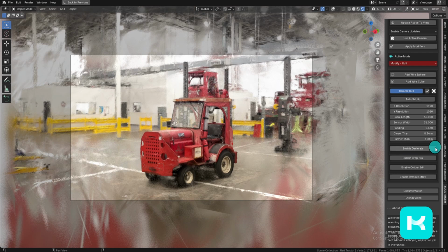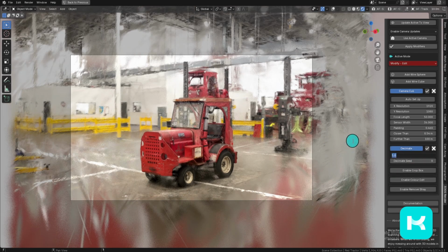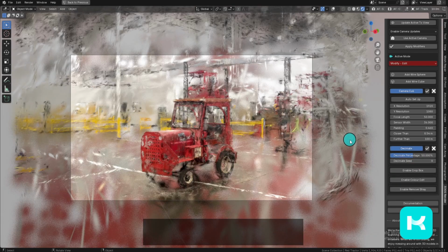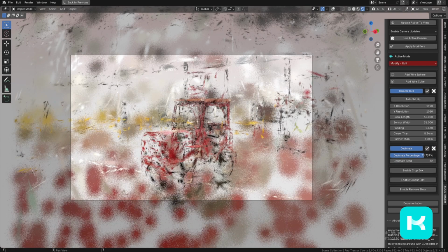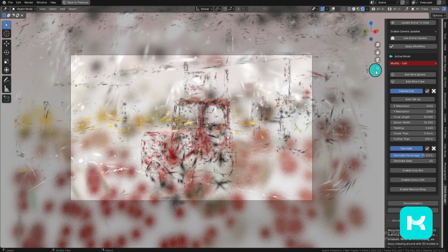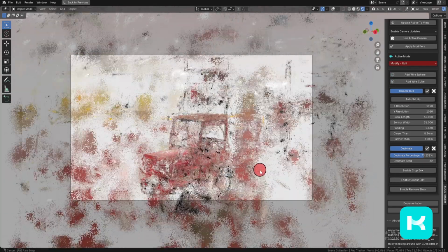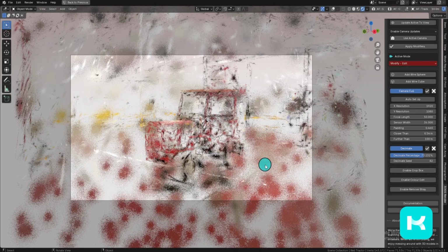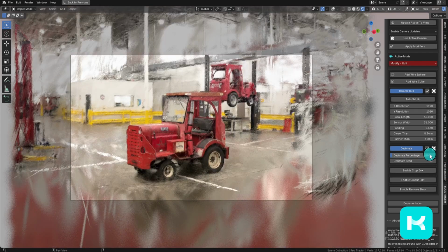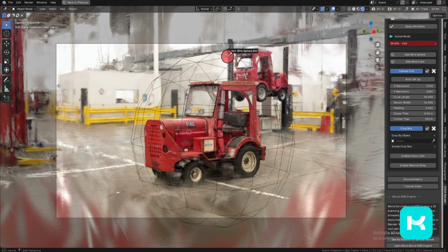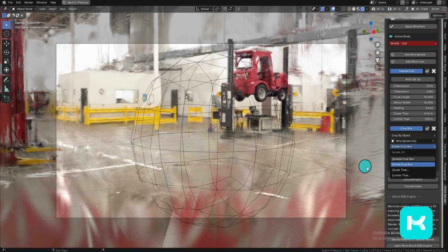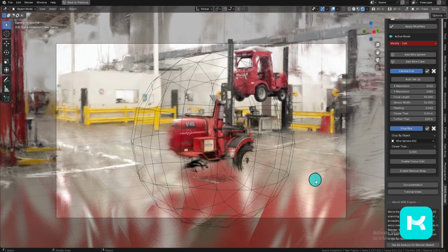Decimate will remove a percentage of the total number of faces from 0 to 100. The decimate seed will change which faces are removed. It can be useful to use a high decimate number while working to improve performance, then drop this number during rendering. Removing any number of faces is helpful, so a low number like 5% can be used and the modifier applied to improve performance.